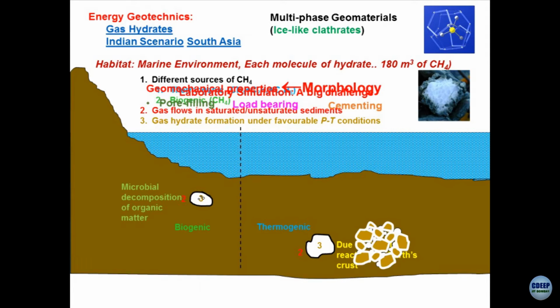So, most of the tests which you did in the laboratory were under soaked condition, whether it is CBR, hydraulic conductivity, shear strength, or triaxial consolidation. You saturate the sample for enough time so that the air phase gets lost. So, truly speaking, conventional geomechanics does not capture the real life response of the geomaterials, and keeping this in view, people have started working on the unsaturated state of the material.